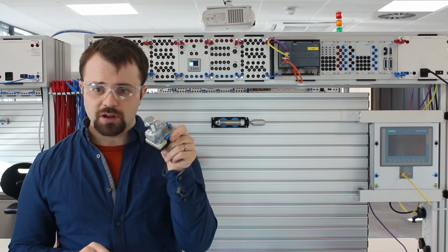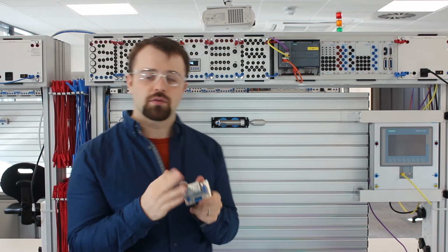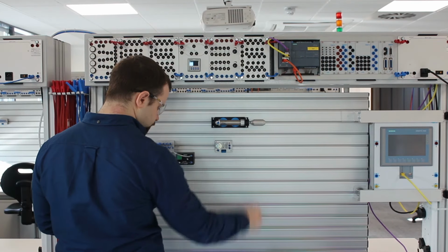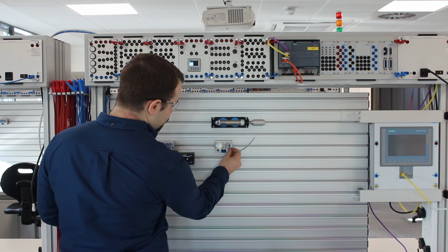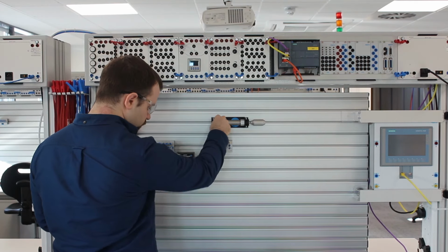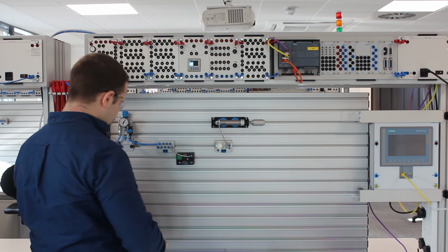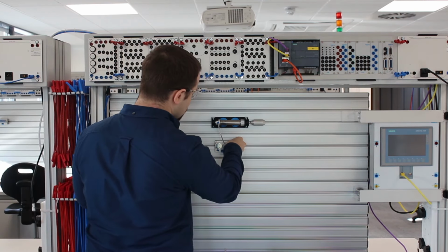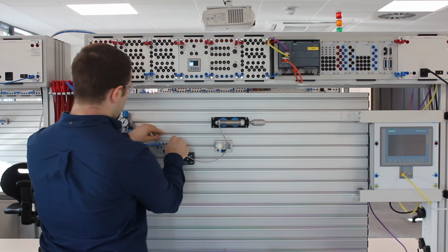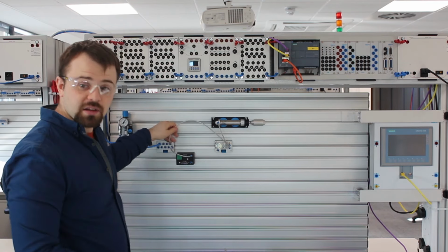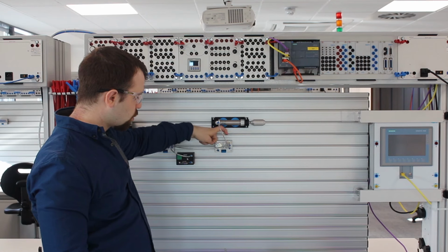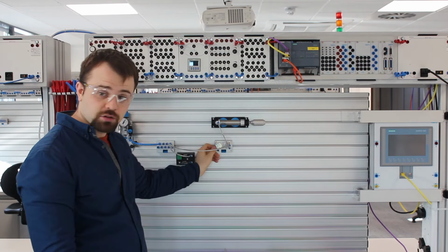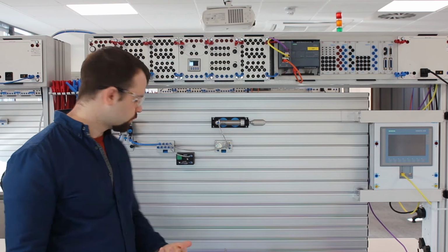This is currently set to 5 bar, and you do that just by turning the knob. I've set it to 5 bar already. So we can attach it to our system. We can take air from 2 to our piston, and we can provide an air supply from 1 through to our manifold. So remember, by default, air just coming from our manifold, waiting and then going into the cylinder. It's not going to go into the cylinder unless the pressure on 1, 2 reaches the right amount.